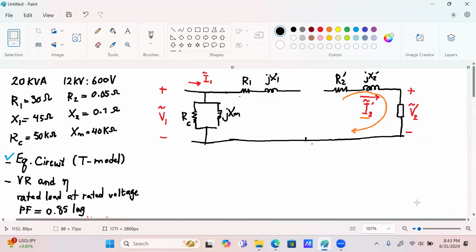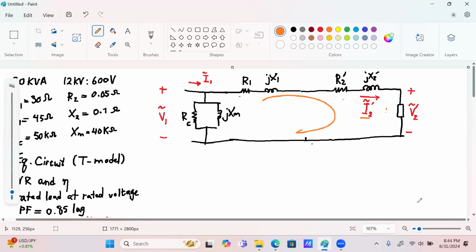So this is my line now, and I do not need this loop. If I move that shunt branch to the beginning of the circuit, this is the equivalent circuit that I will have. The analysis of the shunt branch is really easy. You have the voltage across it, you can find the current through it. So what we really have to do is to solve 1 KVL for that one loop that I have. Notice that instead of solving 2 KVLs and 1 KCL, all I need to do is just 1 KVL.